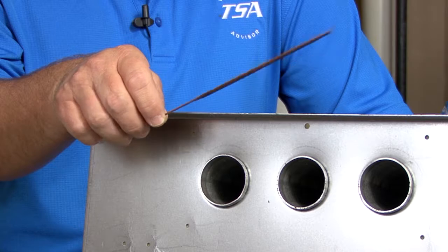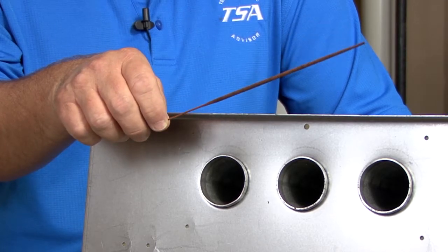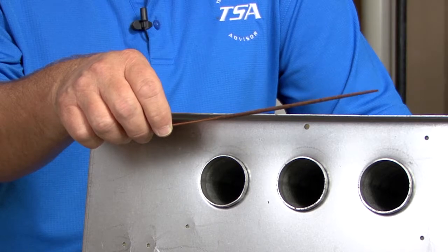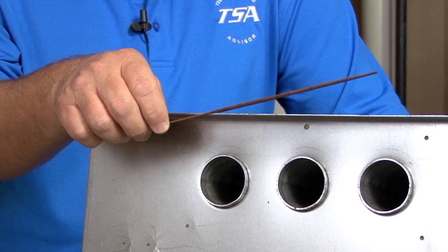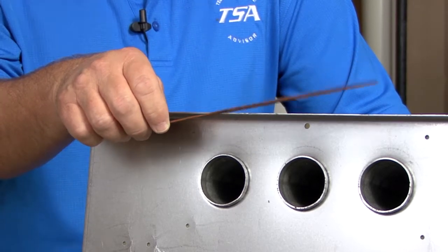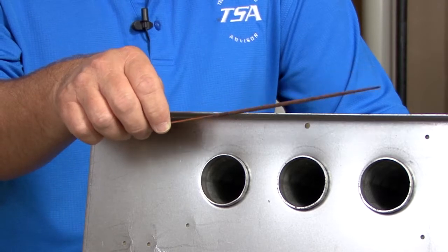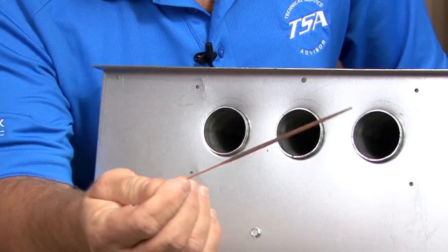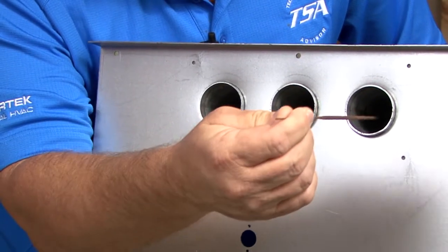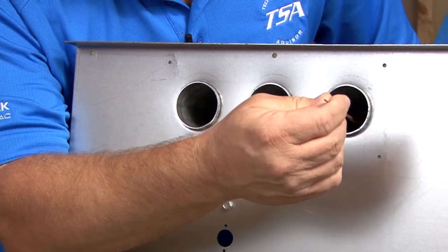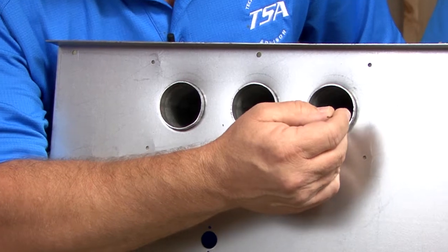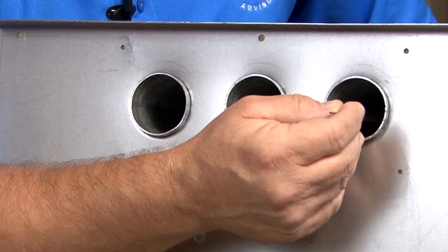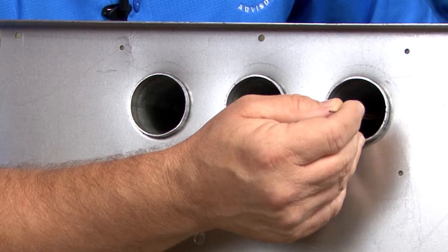And the reason why we tell you to use an incense stick and not a smoke bomb is because we need to control how much smoke we're putting in here. We don't want to use a smoke bomb, that's entirely too much smoke. With an incense stick, we get just enough smoke so we can see where it's going, we know what it's doing. And all we're going to do is get this thing lit up, and we're going to feed that smoke into each cell of that heat exchanger way up in there and just kind of hover it right in the middle. But like I said, as we're doing this, we've got the furnace blower running.